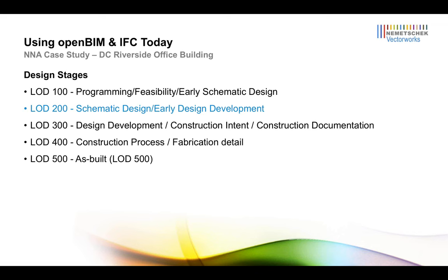At LOD 200, all you need to know is that something is an opening, that the door exists and that there's a location for it. When you get to LOD 300, is it a swing door, is it a sliding door? At 400, is it a wood sliding door, a wood swing door, a glazed swing door? And at 500, who's the manufacturer. So you have that level of detail that applies to each individual component, part and parcel with the project itself.